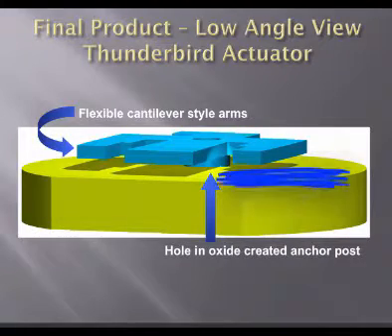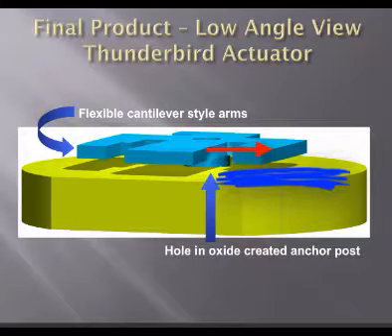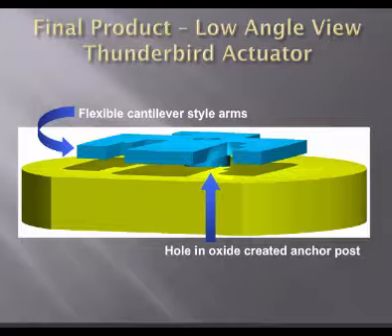If we had like an electrical plate here, and put a positive voltage, and then this was grounded, then the negative electrons would go towards the positive, and then you have negative and positive, they'd attract, and you can get the wing to bend. And then you let go of the voltage, and the wing would pop back up because of the spring constant of the structural material.